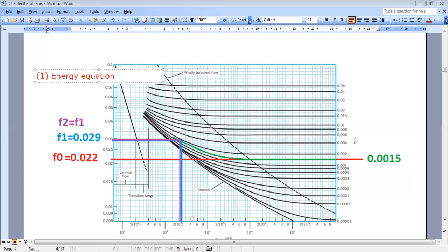Okay. Now, a second relation will be to write the Reynolds number equation, because Reynolds is rho Vd over mu. So when you write Reynolds, you can relate Reynolds to velocity. Sometimes if velocity is given but diameter is not, I get Reynolds function of D. So it depends on the problem. Other equations that I can write, for example, is Q constant. Here, when I wrote that Q is constant, I got that V1 is equal to V equal to V2. Okay. Now, here, Q constant is already used for the energy equation.